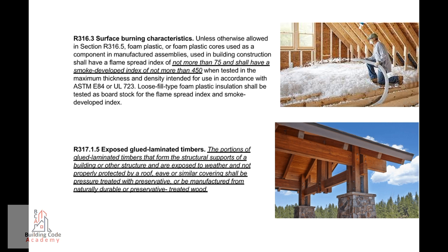Loose fill-type foam plastic insulation shall be tested as board stock for the flame spread index and smoke developed index.